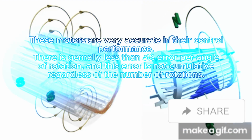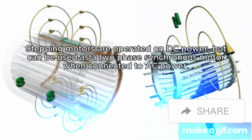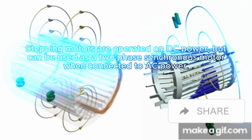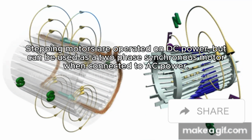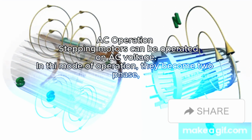There is generally less than 5% error per angle of rotation, and this error is not cumulative regardless of the number of rotations. Stepping motors are operated on DC power, but can be used as a two-phase synchronous motor when connected to AC power. AC operation: stepping motors can be operated on AC voltage.